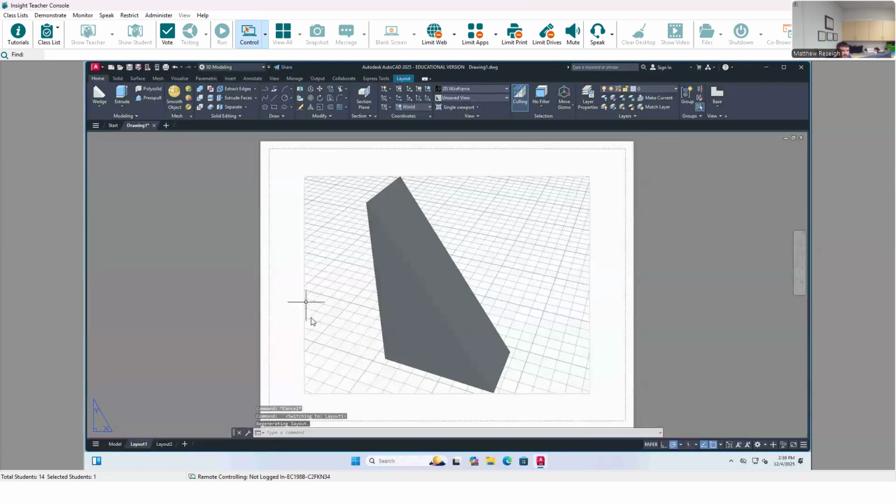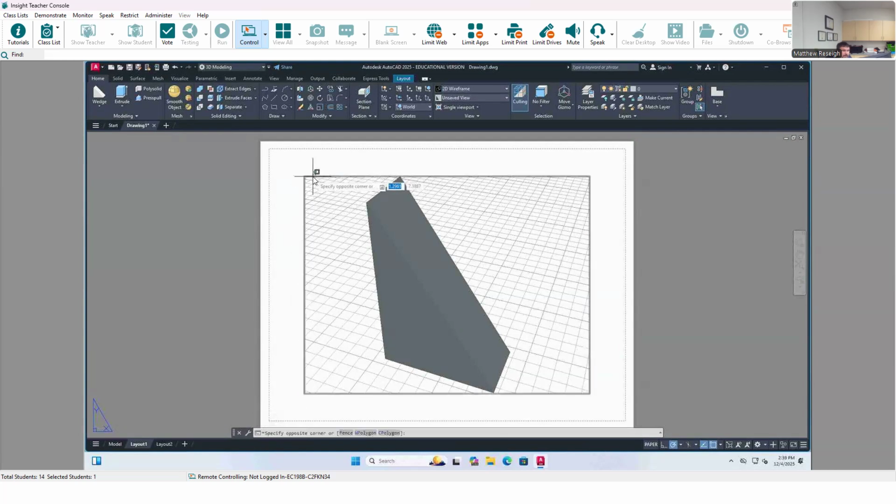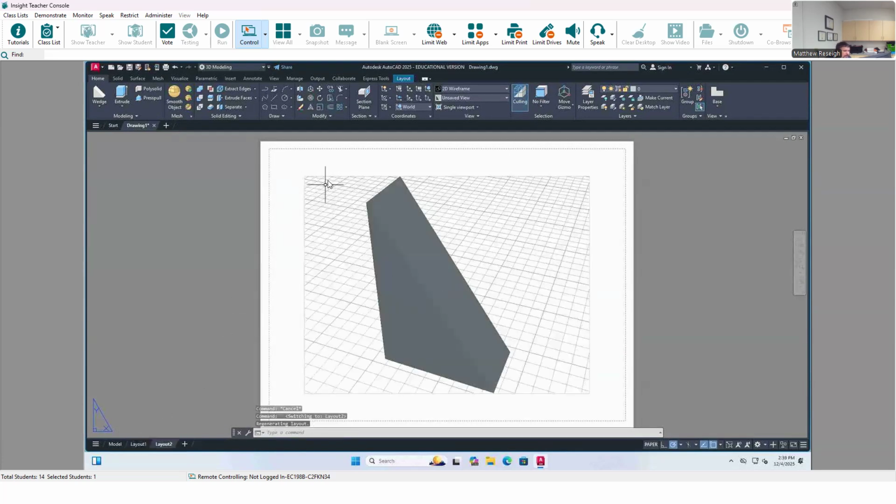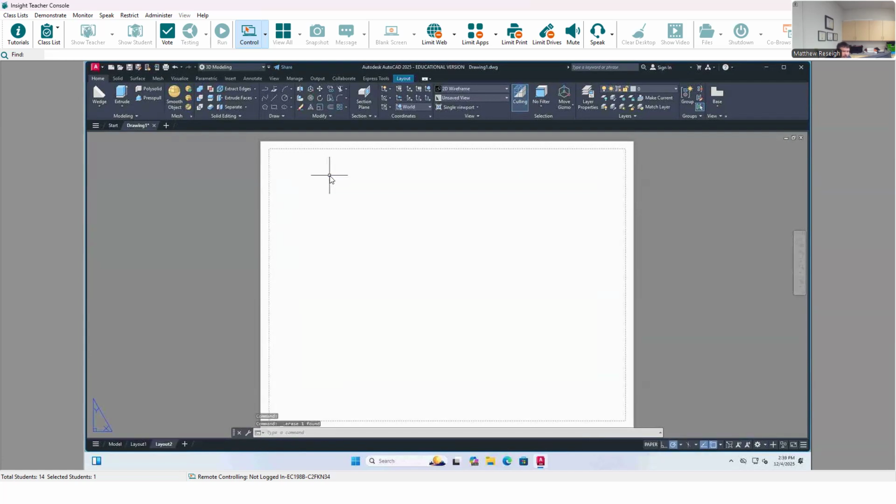The other thing I'm going to do is, on my template, I would have a B size sheet. On here, we just have our viewports. These are like default viewports, so I'm not going to use the viewports to do this command. You can go into whatever layout we have, because like I said, I wouldn't be starting from scratch here. I would want to start from my layers that I already have established and just turn my thing into a 3D template. I don't need to really create a new 3D template. I can just change it into one.